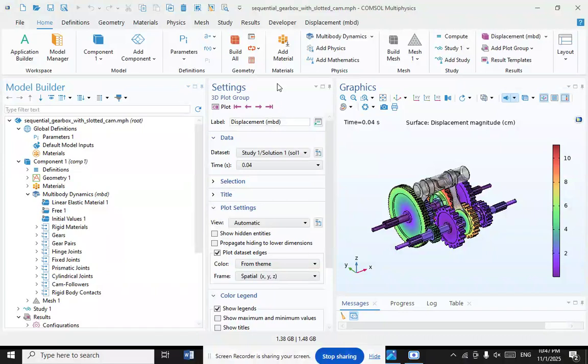Some automatic transmissions are based on the mechanical build and internal design of a manual transmission but have added components such as computer control actuators and sensors, which automatically control the timing and speed of the gear shifts and clutch. This design is typically called an automated manual transmission or sometimes a clutchless manual transmission.